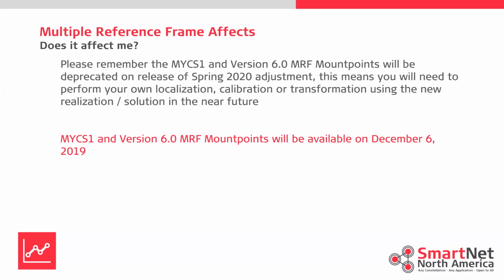Again, please remember, NYCS1 and version 6 MRF mount points are going to be there for you. They're going to help you bridge the gap, but they will be deprecated. Okay, they will be turned off when the spring adjustment happens in 2020. That typically happens end of April, 1st of May. That means you need to perform your own localization, your own calibration, your own transformation using the new realization or solution as soon as it's available. So when it goes live, you need to update.